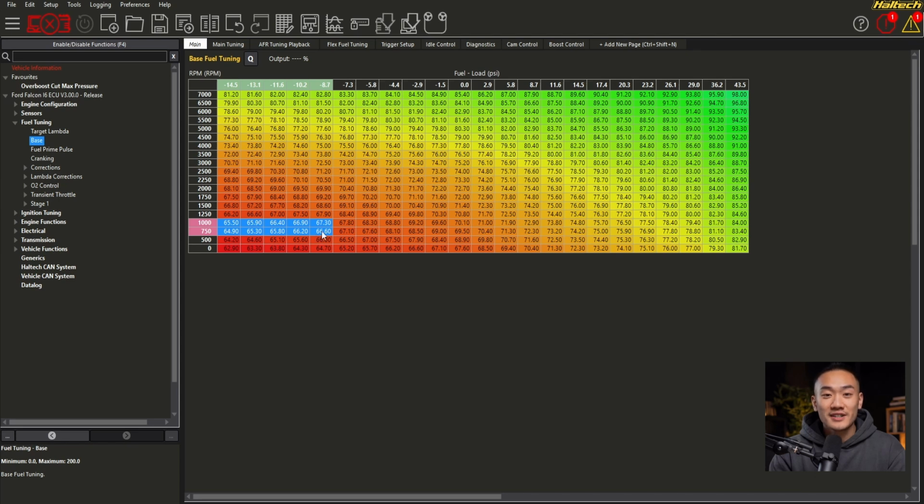If your engine idles cleanly at lambda 1, but the VE value at idle is 80 or 90%, that's a red flag. The engine cannot physically fill the cylinder that efficiently at idle. Something else is wrong, and the VE table is compensating for it. Common causes include incorrect injector data, incorrect fuel pressure, or an incorrect stoichiometric setting.